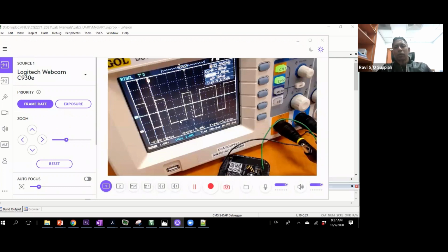Okay, the least significant bit goes out first and then followed by the most significant bit. And once you finish, so if you look at the right side, once I finish, I pull the line high. That is the stop bit. So the transmitter will pull the line high to indicate that it is stopping this current data packet transmission. Okay, so this is basically what you will observe, all right, when you probe your transmit line.